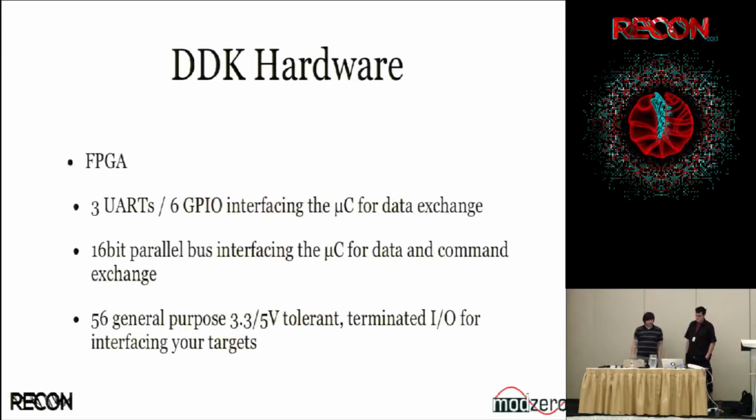Okay, but we also have the FPGA. In terms of you trying to do custom things on it, we chose our pins carefully. The other thing which can go terribly wrong if you're designing your own board is that you'll have the worst combinations of signals ever connecting two chips on your board. So in this case, we thought about what somebody who wants to do something completely custom with this board will want.